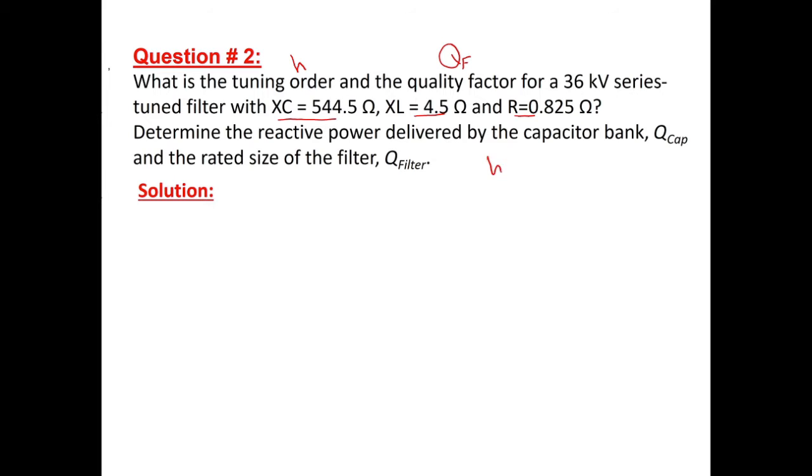We know that the harmonic order will be equal to the square root of XC divided by XL. Everything is given, so we can find the tuning order.